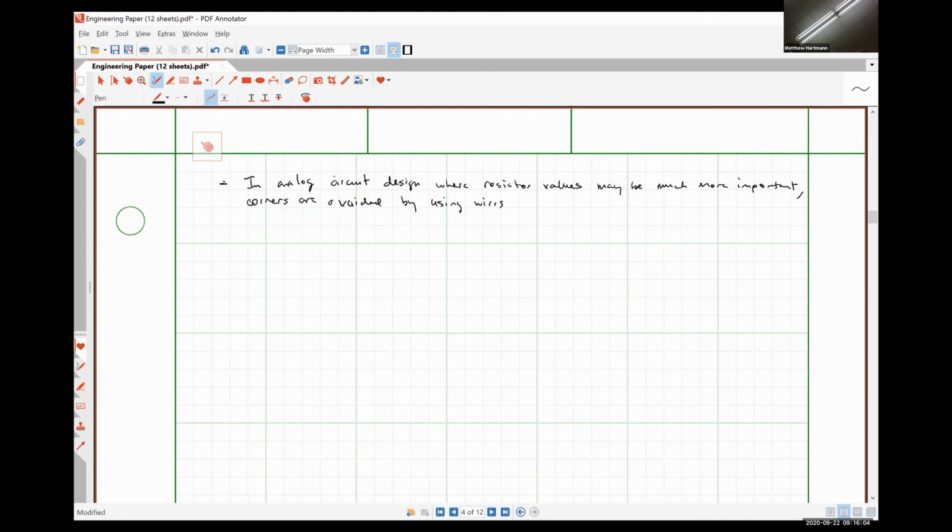So we would actually be using what's called a via, which is a means by which to connect metal 1 to our N-well. Actually, we would be using a via and an N+ implant, which we'll talk about a little bit later.